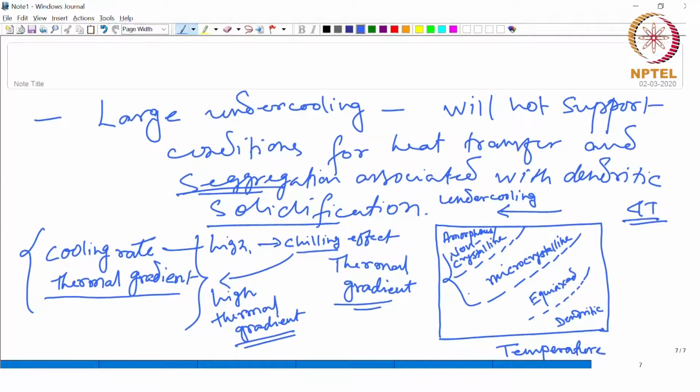So, that part also comes under this microstructural control, because going from a crystalline material to a completely amorphous or non-crystalline kind of structure can lead to a dramatic change in the properties of the material, right. So, it is also important for us to understand as to how these parameters will affect this transformation from a crystalline material to an amorphous material.